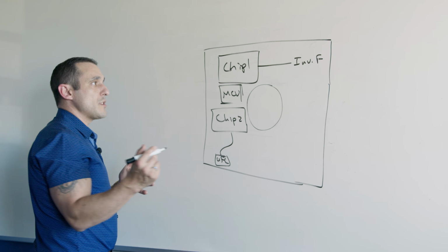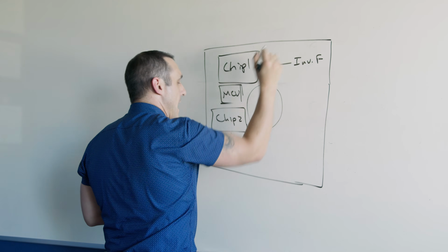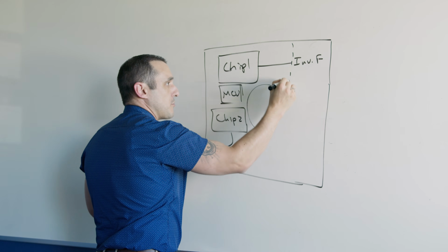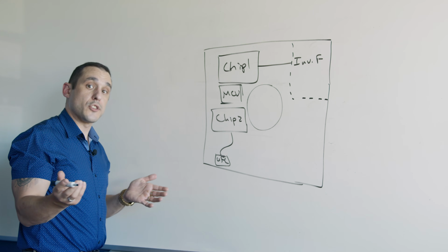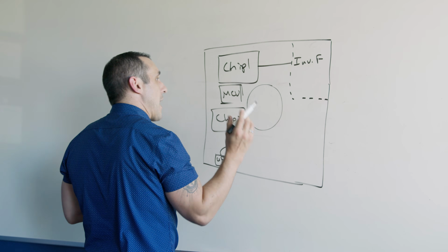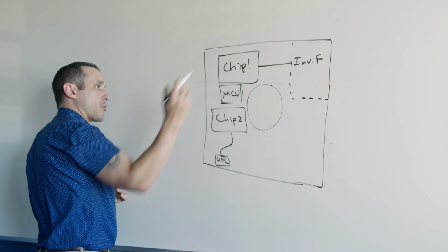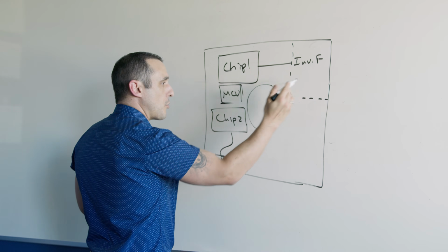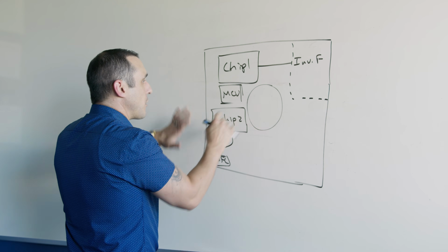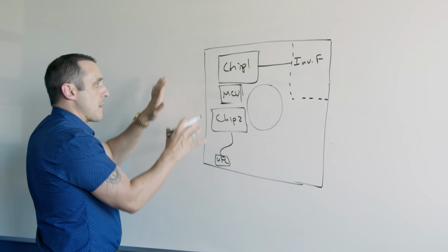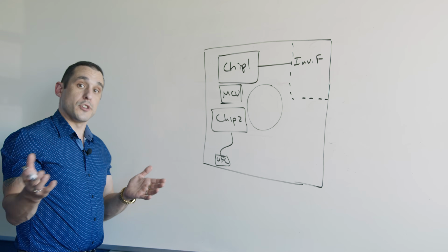Another reason that you want to do that is because, for example, if you have a printed antenna, you're going to have to put a ground cutout, assuming that this is meant to be an omnidirectional antenna. So we want to have this ground cutout here. And by putting this ground cutout somewhere in the corner of the board or along the edge of the board, it's not going to interfere with any of the other routing in the board, and it doesn't take up any of that real estate for, for example, your digital signals.